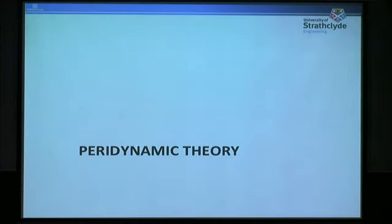Then what do we do? We need to do an approximation. And the name of the approximation is called continuum mechanics. So according to continuum mechanics, what we are assuming is each structure is made of small volumes that we call material points. And as you see, as opposed to molecular dynamics, these guys are just touching each other. So there is no gap in between them. So that's why we call this a continuum by itself.